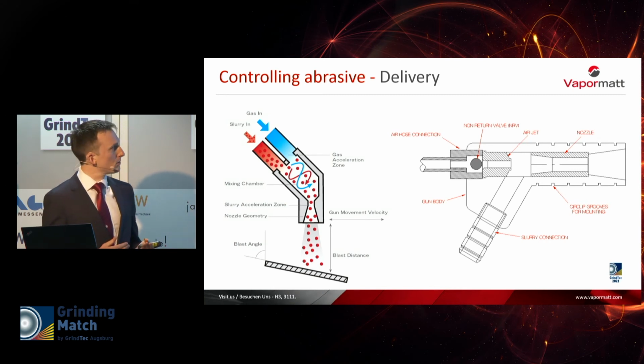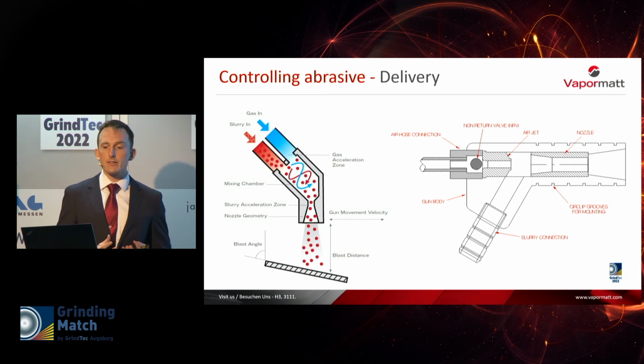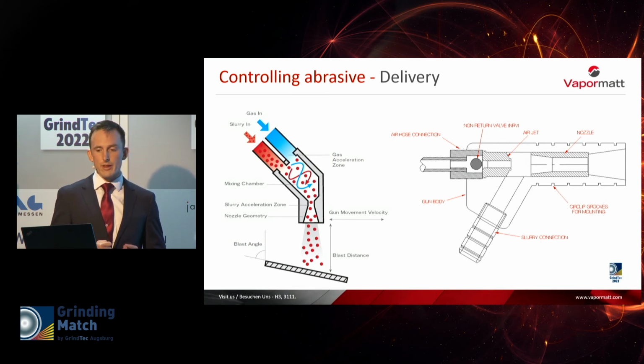The guns themselves also need to be considered, and the wear rates and the angles and the pressures will have an impact on the hone. So, for example, a 60-degree blast angle is faster, but affects the K factors should you be looking to specify different ones there.